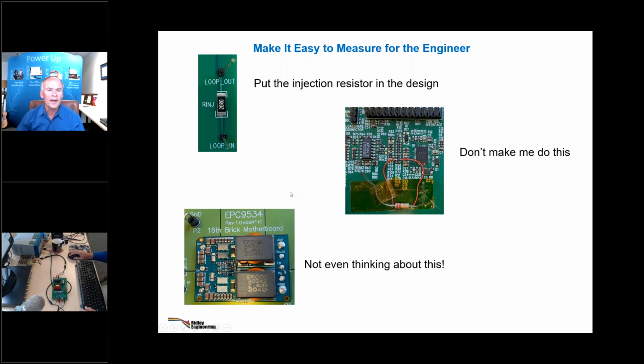All right, anybody out there who works for the semiconductor companies or people that write app notes, please pay attention to this slide, because while we all recognize that loops are important, there are many machines for measuring loops. Everybody wants to do it now. When people are making app notes or designing their power supplies, they're making it harder and harder and harder to cut into the loop, which is why they say, well, don't do that, measure the impedance instead.